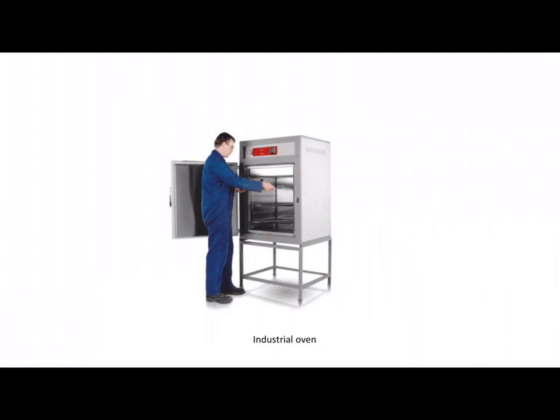If you're working with plastic and you want to form your plastic, there are different ways in which you can do it. One way would be to heat the plastic uniformly, so that you can then put it in between two halves of a mould, and that is called compression moulding. And in order to do that, you need an oven like the one on the screen.